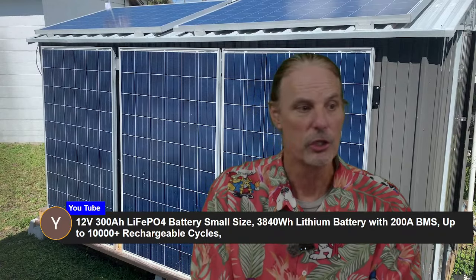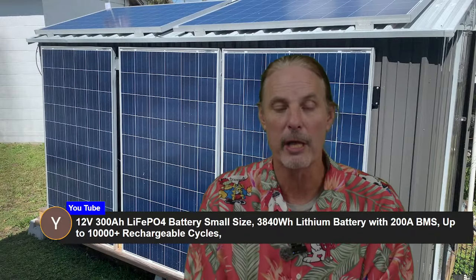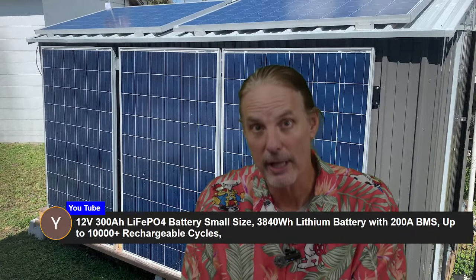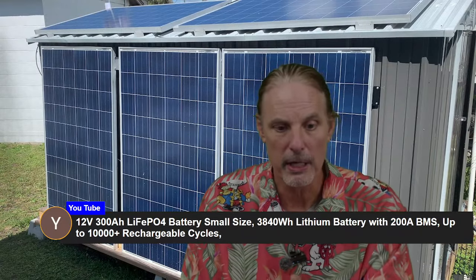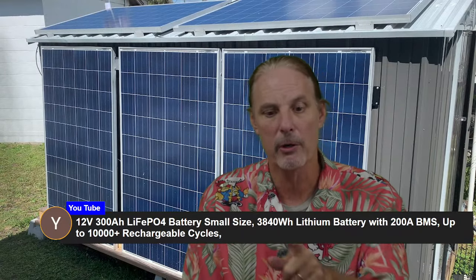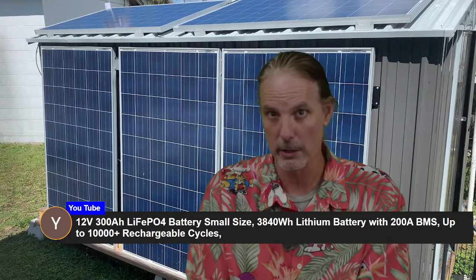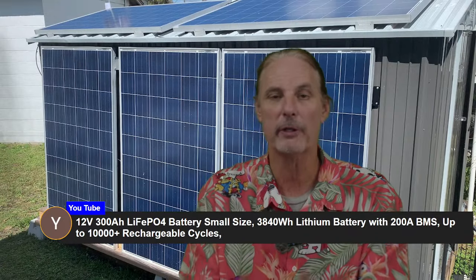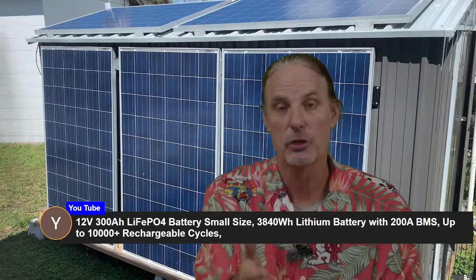In this case, Brian from Oklahoma has a 200 amp hour battery. Most likely you have a 100 amp BMS, whereas in the case of YouTube here, he has a 300 amp hour battery with a 200 amp BMS. So the BMS size is what's important here. So we want to do two calculations. The first one I would say is what size amps does your BMS support?